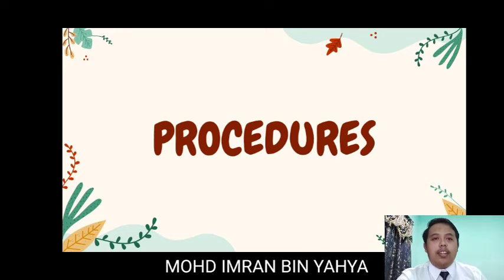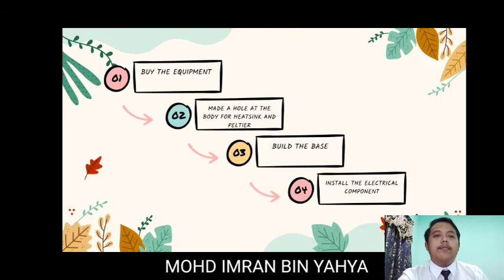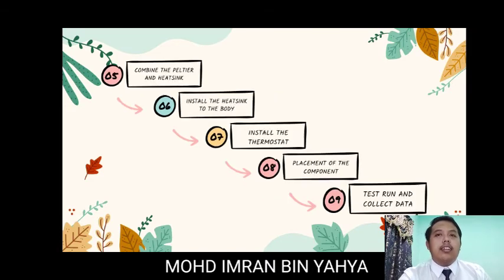Next I will explain the procedure of our project. The first step is to buy all the equipment and then make a hole in the body for the heatsink and Peltier. After that, we build the base, and next we install all the electrical components, and after that we combine the heatsink and the Peltier. After combining the Peltier and heatsink, we install the heatsink to the body, and after that we install the thermostat. Next we place all the components, and lastly we test run the project and collect data.